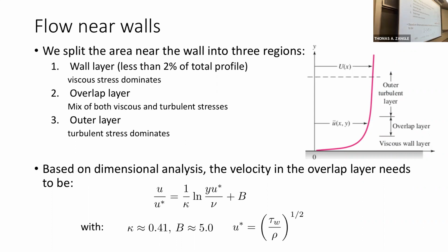Works for any fluid and any surface? Yeah, this fit should work for any fluid and a smooth surface. We haven't talked about roughness yet, and roughness is going to be important. But this works for any fluid and a smooth surface. That's correct. And we're going to extend this to a tube in the next couple of slides and use this to find our velocity profile.